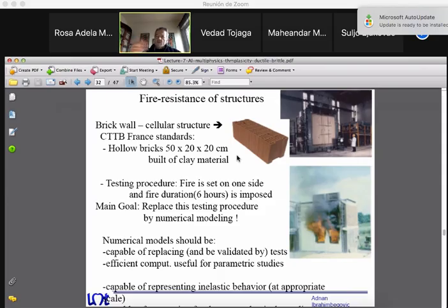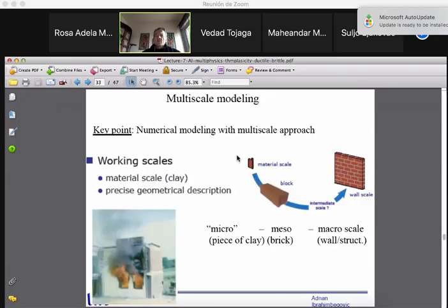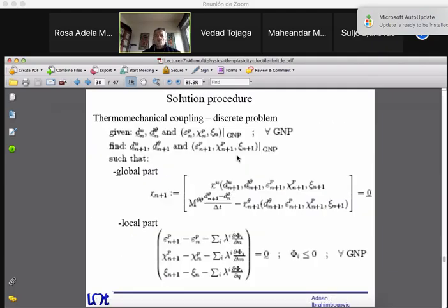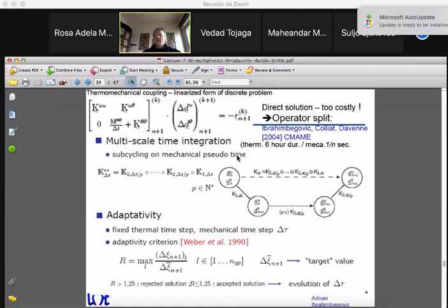So you have a time scale of evolving the temperature, which is very large compared to the evolution of this plastic strain and the damage variable that are representing the failures. So basically, if you start computing this in time, using the 10 time step, of course, what you're doing is really something which is not very meaningful. So if you really want to last for 6 hours in terms of computation, if you take a fraction of a second, you're going to have many steps. And you could see that many of these time integration schemes will be in big trouble by doing so. So basically, we better change this type of idea.